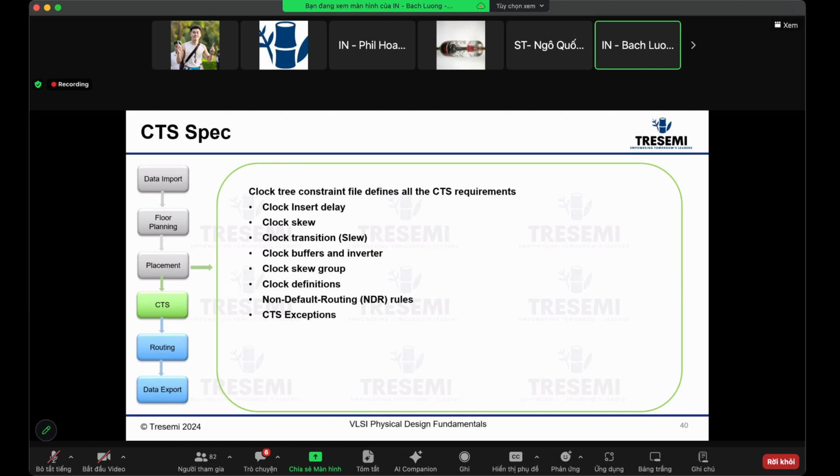More loading, exactly. So more loading, what does that translate to from the clock tree standpoint? It's more capacitive load on the clock nets. That's correct. Keep thinking. So more load, more routing resource, but more loading on the clock. So when Wu Tanan said consume more power, that is correct. Absolutely, that is the point to make. So that is consume more power.